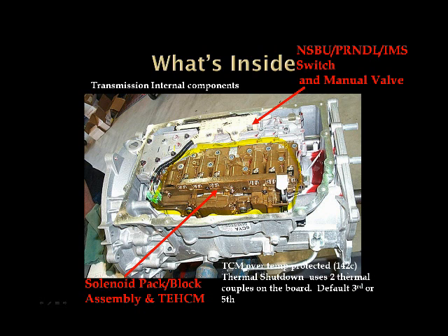So the TECM consists of your solenoids. As you can see, we've got solenoids here, here, here, and so forth across the base of the TECM itself. The TCM is right in this area right here. And along with that, you're going to have some pressure switches built into the base of the TECM, and you're also going to have some temperature sensors built into the TECM. There's actually 3 temp sensors in the TECM assembly itself. 2 are thermocouples mounted on the circuit board itself that are used for over-temp protection of the TECM.